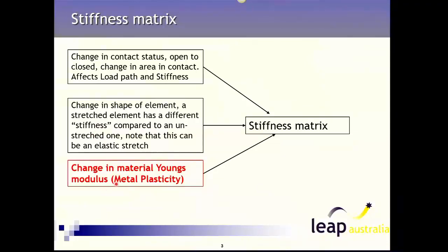Okay, also in line with this is the amount of strain. Normally for most metals, when you get to yield, the strain is quite small, only a fraction of a percent. But materials like rubbers can undergo quite high strains, sometimes of the order of 200 or even 300%, and that deformation can be recovered. So it's not only when you have permanent deformation that it's considered a material nonlinearity, it's also when you have strains that are quite large. Usually when you get up to, say, 5% or above, you generally need to calculate your strain differently. That is only taken into account when you turn on nonlinear effects. Your strain is calculated as a log strain.